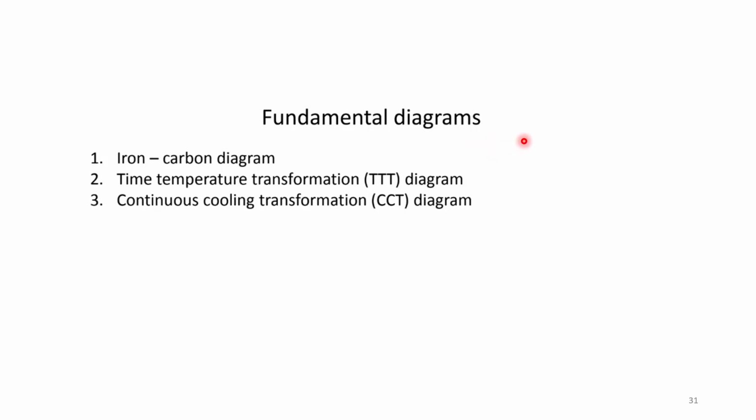Fundamental diagrams. These three diagrams are of very high importance in studying heat treatments. One is the iron carbon phase diagram, iron carbon or iron carbide diagram, then the time temperature transformation diagram, and the continuous cooling transformation diagram.